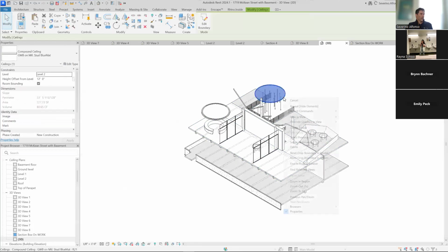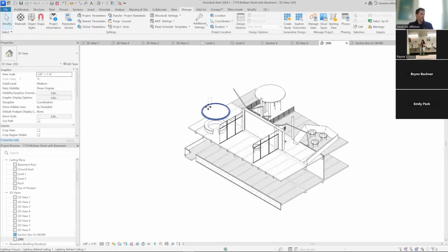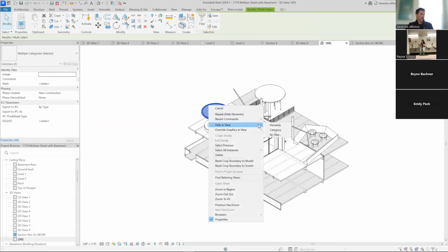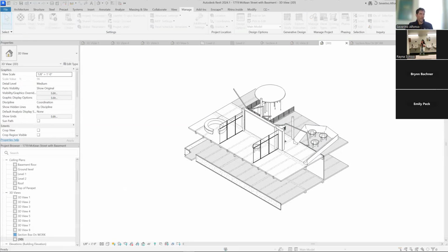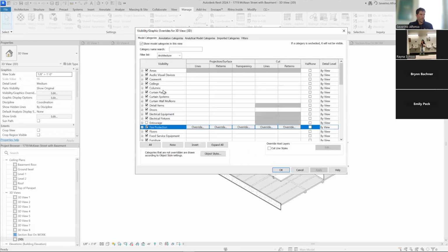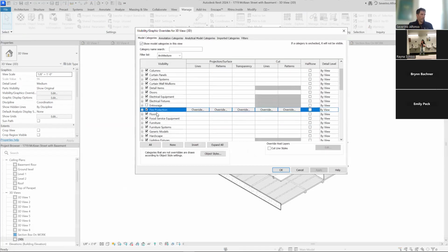And then the question here is, how can we assign to different furniture pieces in a diagram different colors, no? Because what I can do is assign diagrammatic colors through visibility and graphics, which is V, no? And I can go to furniture or to any other thing, floors or whatever.